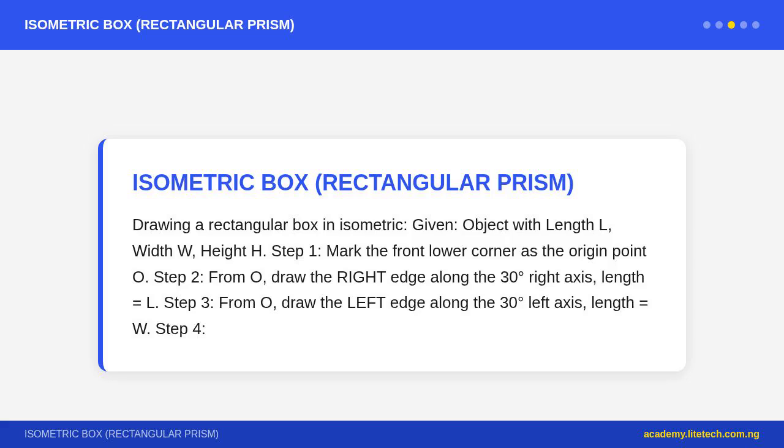Step 2. Find the midpoints of all 4 sides of the rhombus. Step 3. From the 2 acute corners of the rhombus, the sharper corners, draw lines to the midpoints of the non-adjacent sides. These lines intersect to give the 4 centers. Step 4. Use a compass to draw 4 arcs. 2 large arcs centered at the acute corners of the rhombus. 2 small arcs centered at the intersection points inside the rhombus.